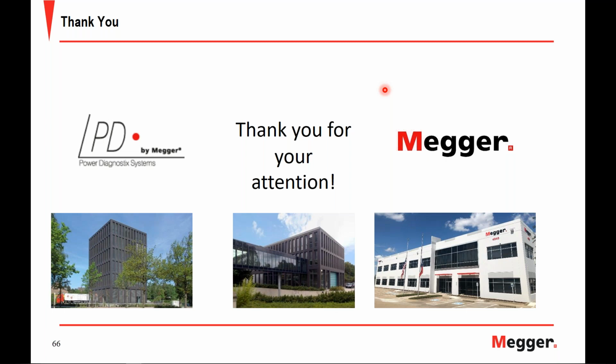It's maybe a bit like on a transformer. As long as your DGA results are good, there is actually not an immediate additional value to have PD monitoring right away. So first, if you start to see signs between offline measurements using the same equipment and same setup versus the reference measurements you had during the FAT, or you see some significant trends in the online periodical tests using the couplers, then it could be worth it to install PD monitoring.